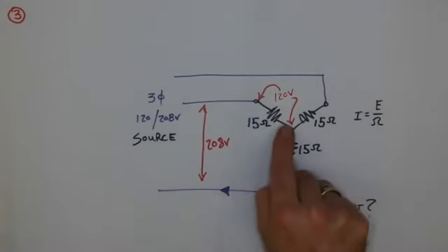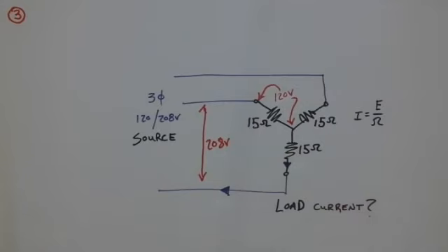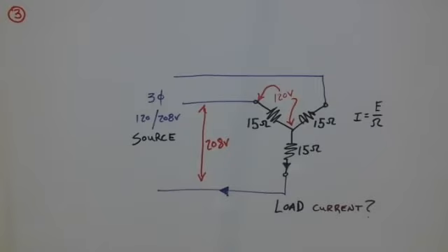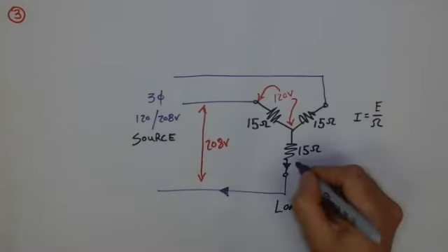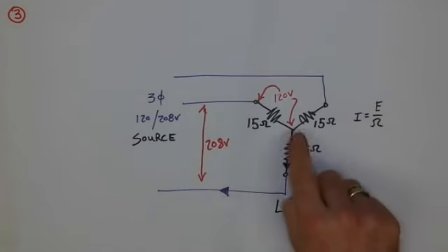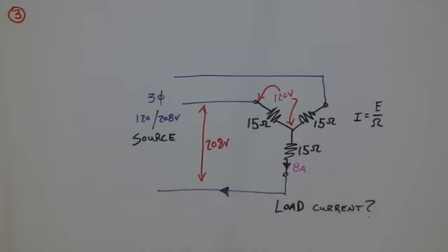Now, if I want to calculate the individual current of a single phase, all I need is a basic single phase equation, which we see right here. The voltage divided by the ohms. So 120 divided by 15, which gives me a grand total of 8 amps. Now remember, if it's 8 amps flowing through the individual phase, it must also be 8 amps that is flowing through the line connection. So in a Y system, we say that yes, the line and the phase value are identical, in this case, 8 amps apiece.